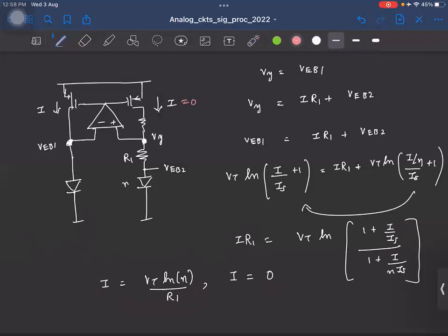If current is 0, what is this voltage? If the voltage is also 0, so this is also 0. So it looks like virtual ground is enforced. So what will be this voltage? Let's call this VDD. This will be at VDD, right? So for the PMOS, gate and source are at VDD, so no current flows. So looks like everything is consistent, right? So if you don't do anything and just make this circuit, it is possible that finally you end up with this dead solution.